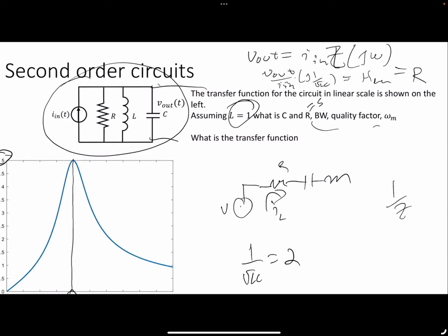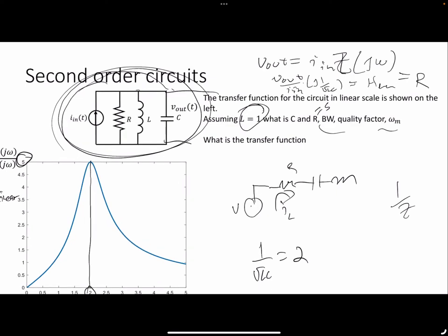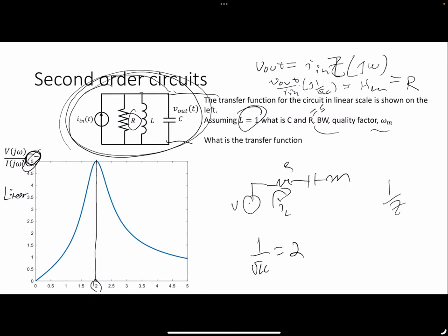Then the rest, I mean, you can just apply a formula to find them. But again, where do you find the R? What is the maximum response you can get out of this circuit? What frequency? Yeah, and at resonance, the impedance is R, and the output is the voltage times the resistance, or the impedance times the current. So as a result, that's how you know that R is the maximum in that graph.